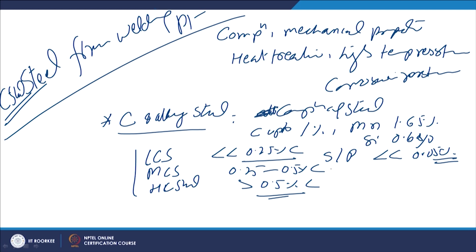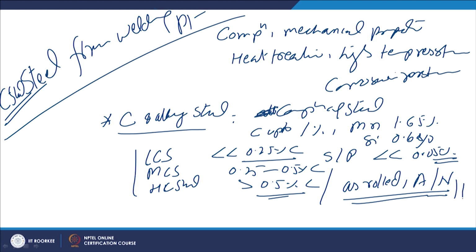And most of these steels are used in as-rolled, annealed or normalized condition. Since the heat treatment condition of the steel significantly governs the weldability, it is important to know about the condition of the steel, or the heat treatment condition of the steel.